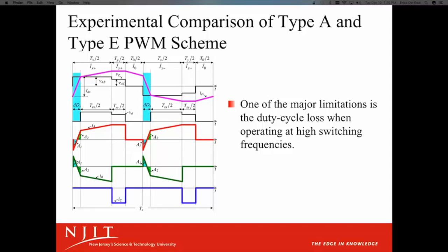Furthermore, a low input current total harmonic distortion (THD) will be able to be achieved with duty cycle compensation. One thing to mention is that the three-phase buck matrix type PWM rectifier is equivalent to a traditional current source rectifier (CSR), with the exception that the switches are bidirectional.